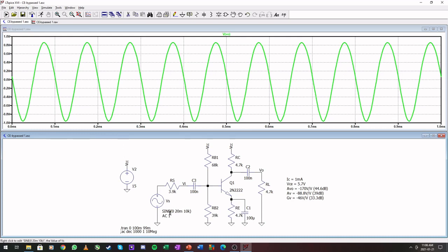Okay, so 10 millivolts peak going into your amplifier as V pi is that edge of being not linear. Okay, 5 going in would be better, as we have at this point with only 10 millivolts here. But this is kind of the edge.